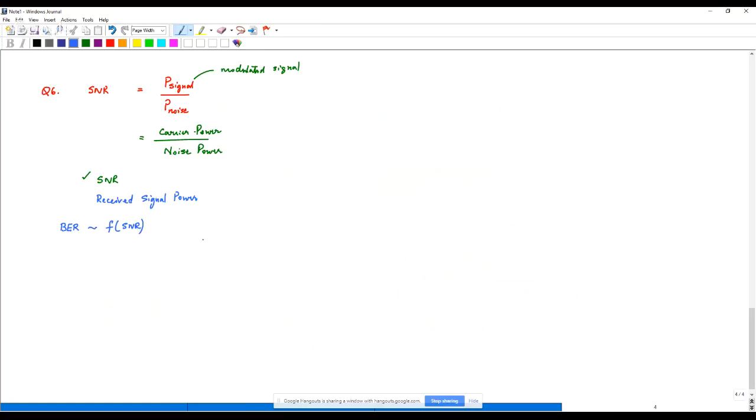If you recall, we did discuss the problem of outage. If this is my base station and this is my edge of coverage, this is the range at which I design my system for coverage. But because of shadowing and other impairments, I may not be able to go all the way to the boundary at some points. In some places, I may be able to go a little farther. So if somebody is in this location, they will not get adequate signal to noise ratio because of the propagation losses. This particular user will be in outage, whereas this particular user is actually seeing a good signal. They can communicate even though they are outside of the range. So this is one of the design elements that we have to worry about. But at the back of our minds, we are always looking to ensure that we maintain a certain signal to noise ratio at the boundary.